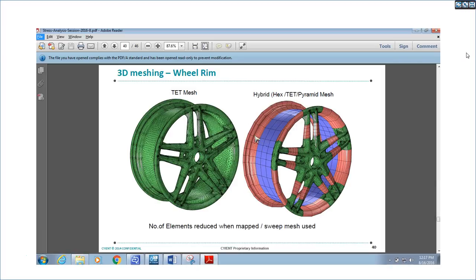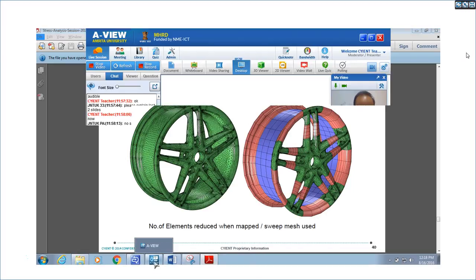they put a sweepable mesh here. Similarly, they chunked it here also. So where we can put a very fine, very good brick mesh here. So to do this tet and brick meshing combination, it is very important for us to do Boolean operations on the CAD model available. So I hope that I answered that question.